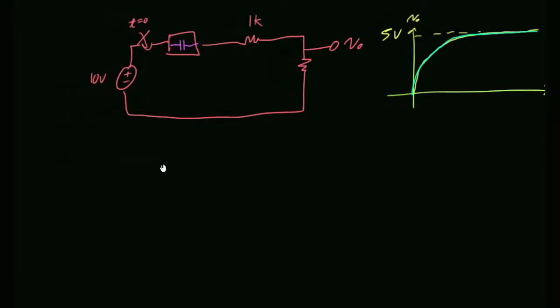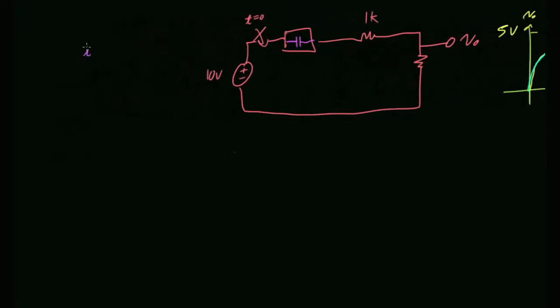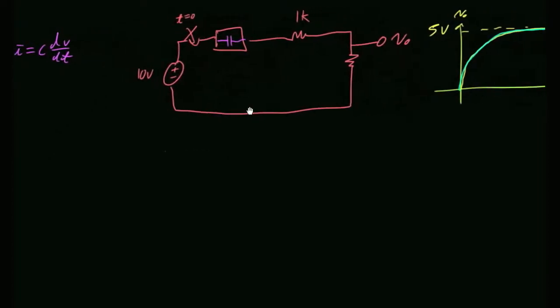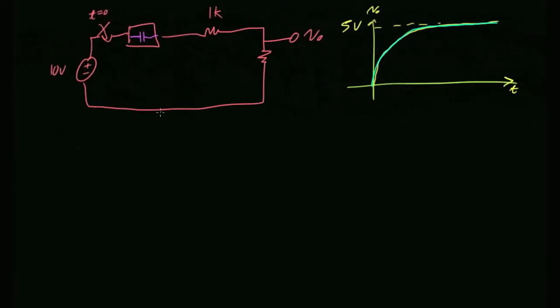So eventually, if you're putting in a constant voltage across this thing, that cap will charge. And when it charges, its voltage will reach a constant value. If the voltage is a constant value, what will be the current across that capacitor once it charges? 0. By definition, once a cap charges, if the voltage isn't changing, there's no current.